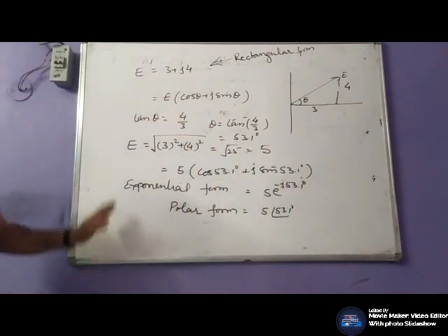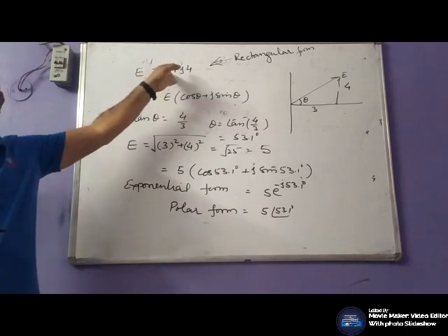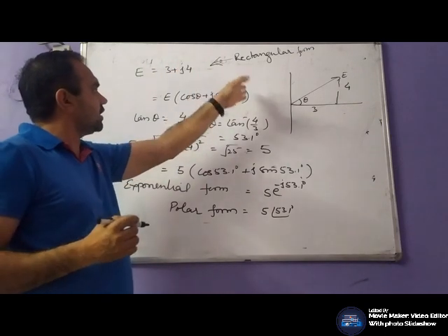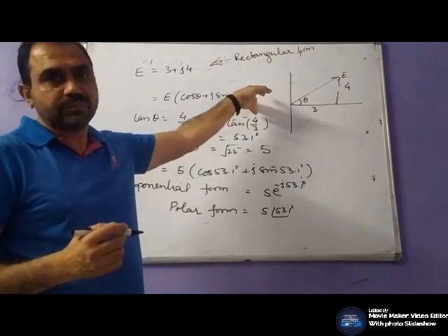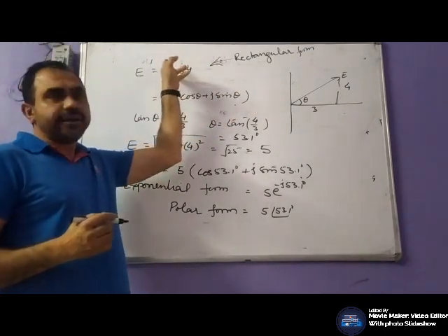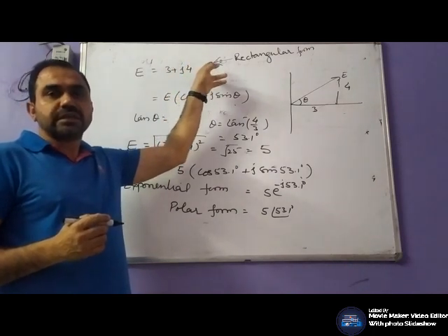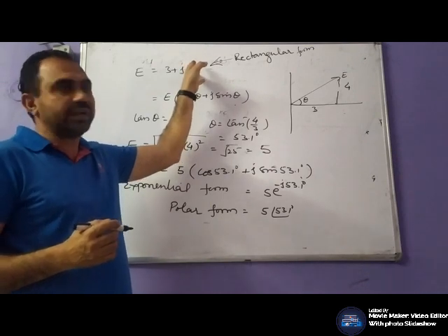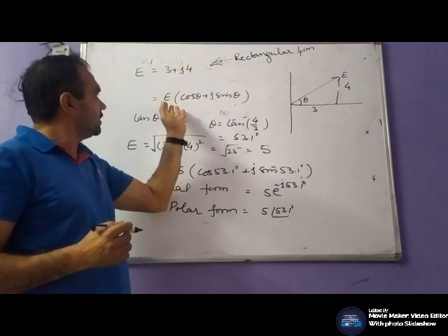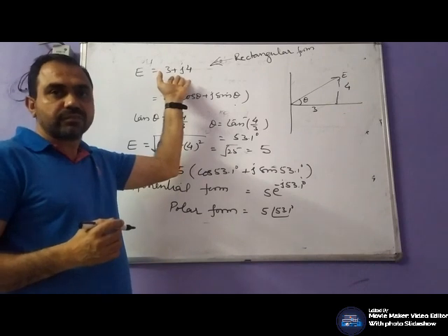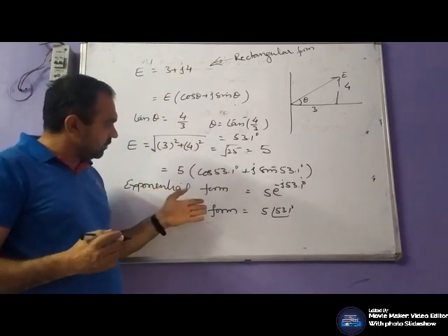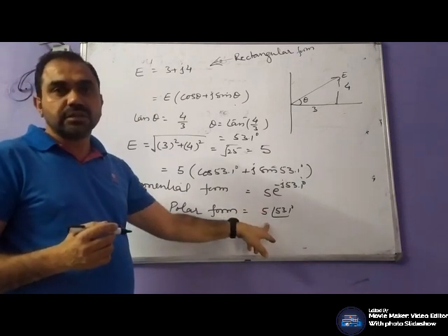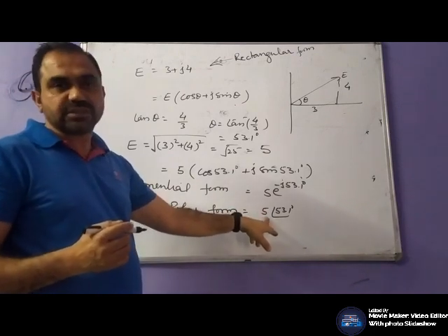Now, addition or subtraction is simple in case of rectangular or trigonometrical form. You just add the real components and imaginary or quadrature components simultaneously, likewise for subtraction also. For multiplication and division, polar form gives better results and saves time.